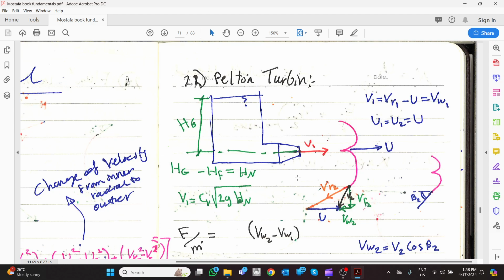In case you have fans, for example, and you're doing a CFD and you have an exhaust fan with a wind in front of the exhaust fan at the roof, you can do this calculation to get the head by knowing the blade angle. No need to draw the fan itself and to simulate the fan while you are concentrating on simulating the building. You get my point. So this is the analysis you need to do, even manually or whatever.